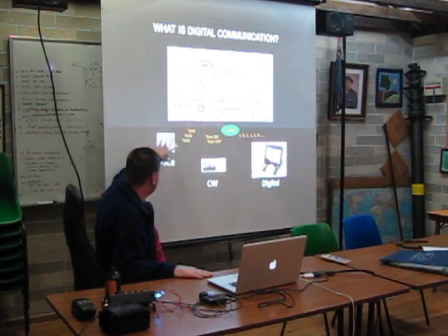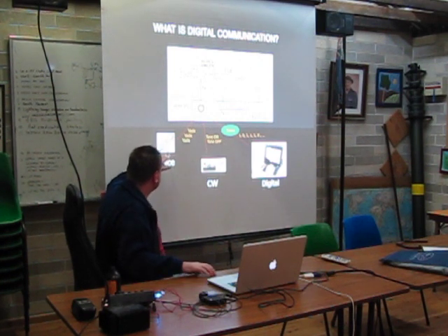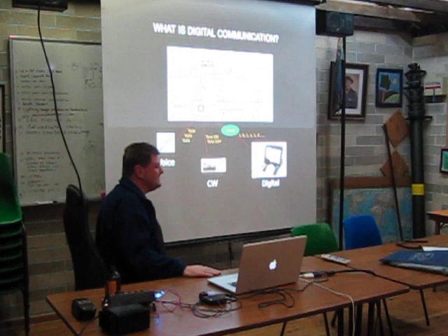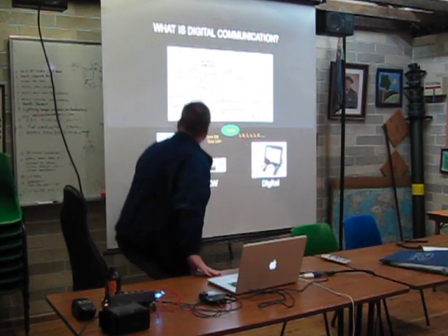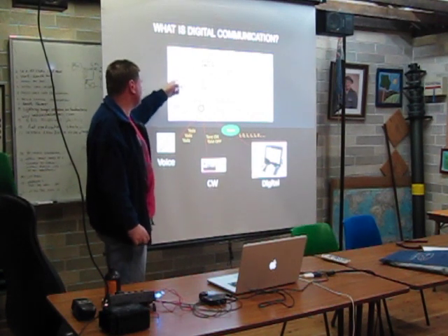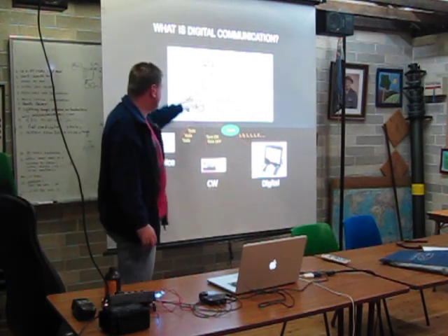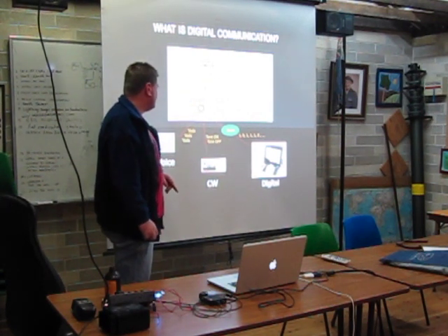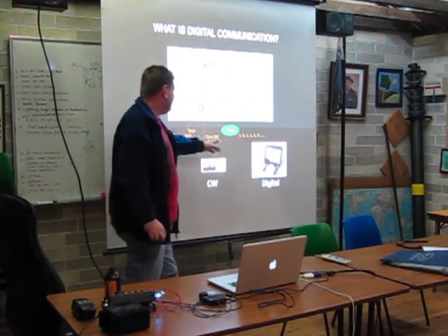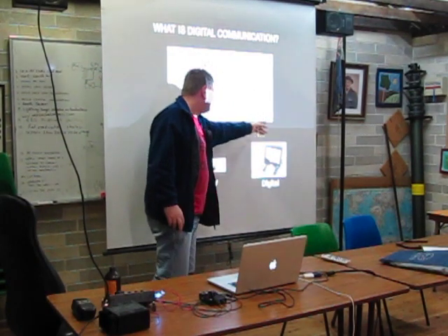You can apply your voice. The audio comes into the audio stage of the radio, and we have a local oscillator, or a carrier oscillator, in the radio. When we mix the two, you get the sum and the difference of the frequencies. The main thing we're interested in here is the sum of the two frequencies.